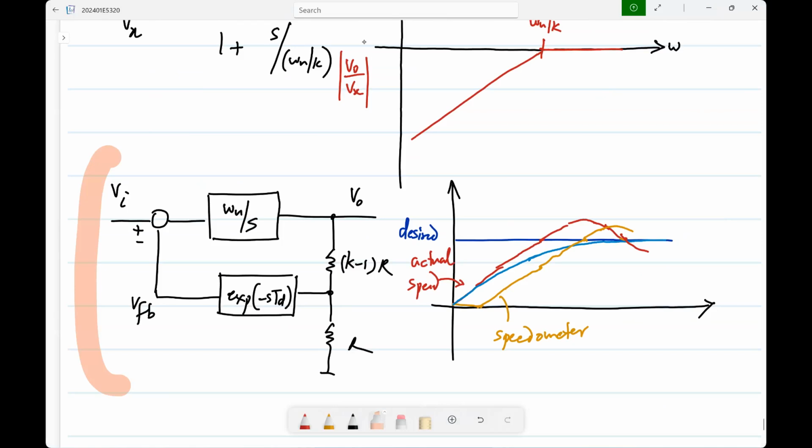But this is the transient part, right? The steady state will still be the same. Yes, it could reach swing limits. Many things can happen. For instance, the power supplies that you use in the lab are also negative feedback systems, so that they hold the voltage to be some constant that you set, right? You set it to 6 volts or 5 volts or whatever. Now let's say you turn on the power supply, it reaches 8 and then comes back. If it is connected to your circuit, who knows, your circuit could get damaged at that higher voltage. So many of these things can happen. That's just one example.